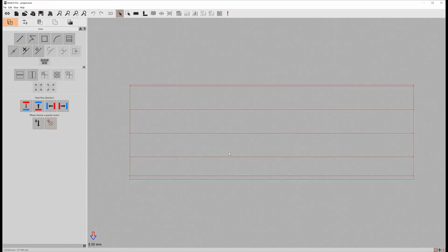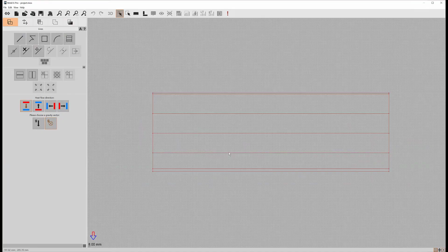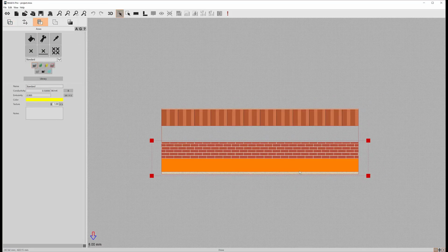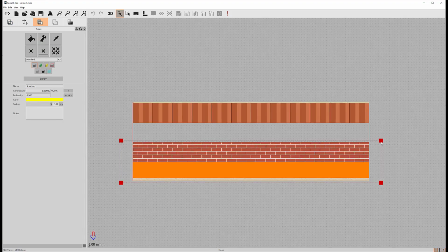Slightly ventilated layers are surface resistances. Mold Simulator finds the right value. Air entering the layer comes from the external environment. External layers are needed for this value but must be excluded before simulating. Grouping them makes toggling easy.